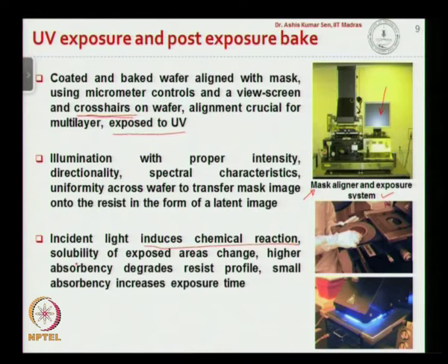So the solubility of the exposed areas is different as compared to unexposed areas. Depending on the property of the photoresist, if the absorbance is going to be higher, then it would degrade the resist profile.